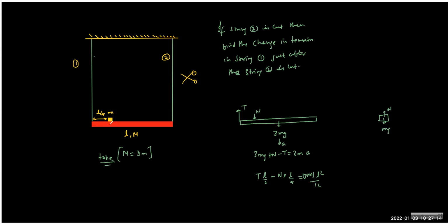Now we need to find the acceleration of this point P in terms of alpha and A. It will be A below and alpha L by 4 above, right? So the net downward acceleration will be A minus alpha L by 4. This you need to realize from kinematics of that point, because that point is part of the plank.